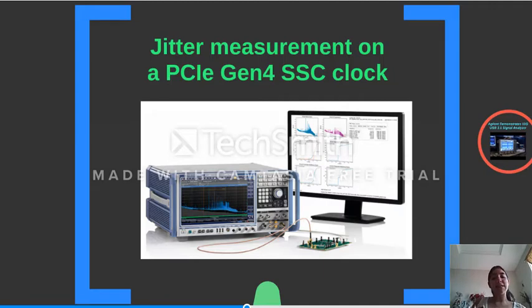To minimize EMI effects, technologies like PCIe, USB, and HDMI use spread spectrum clocking, or SSC, applying a low frequency FM to the reference clock signal, which adds additional stress to the clock. You also need to verify and test the modulation.